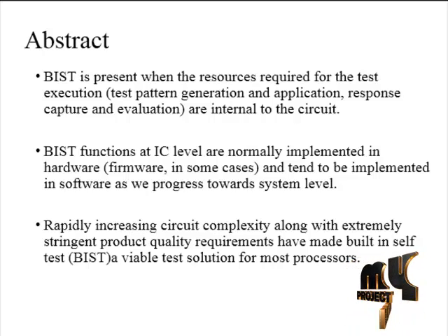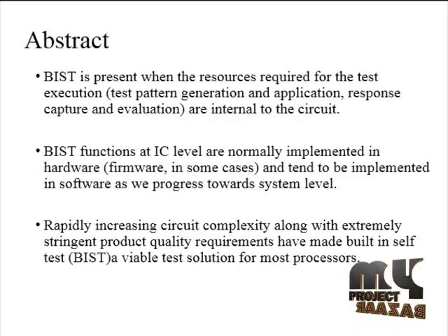One conceivable but expensive solution is to probe the prepackaged dynamic random access memory. The easiest and most cost-effective solution is to add built-in self-test circuitry inside the chip. The BIST engine provides an efficient mechanism to deterministically drive and receive patterns on the memory bus, along with automated data checking capability. These features can be used to swiftly identify and isolate bugs in the silicon validation phase.